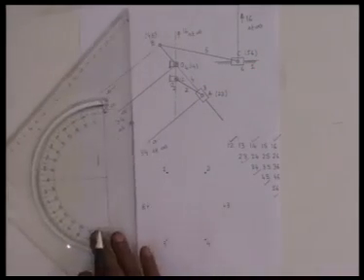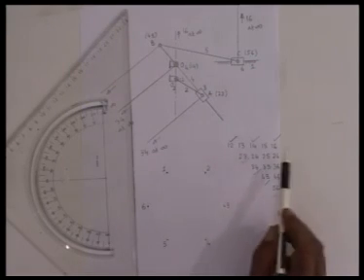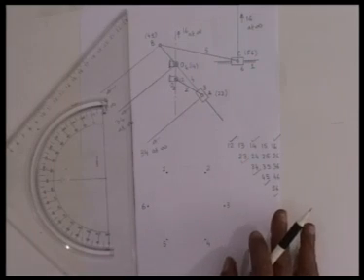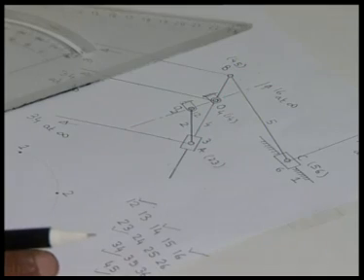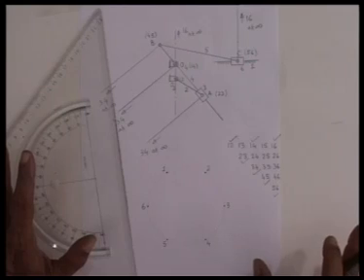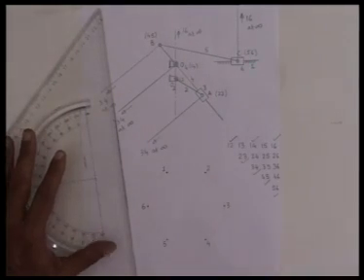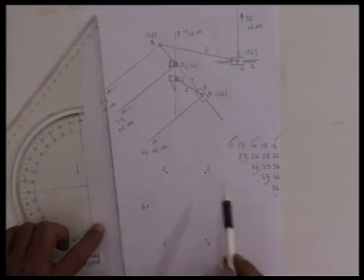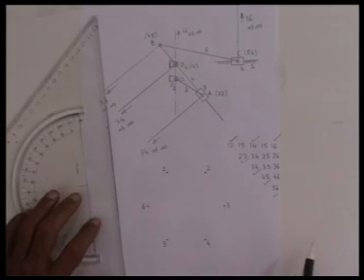So because of the 7 kinematic pairs, we have just by inspection located 7 out of these 15 relative instantaneous centers. Rest 8 can be determined only by invoking Aronhold-Kennedy theorem. But because there are so many numbers, it will be quite confusing if we do it haphazardly. It is better to do it a little more systematically. To do it systematically, I put these link numbers 1, 2, 3, 4, 5 and 6 at equal spacing on the circumference of a circle.